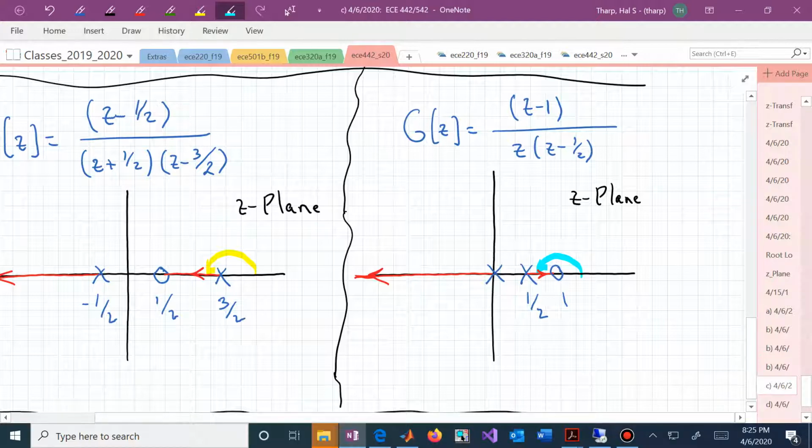And then we have the one pole at the origin, which has to turn through an angle of 180 degrees to get to that point. That's why these two branches are on the specific line segments that are shown in red, and we have one of those branches terminating at the finite 0. The other branch goes off to the 0 at infinity.